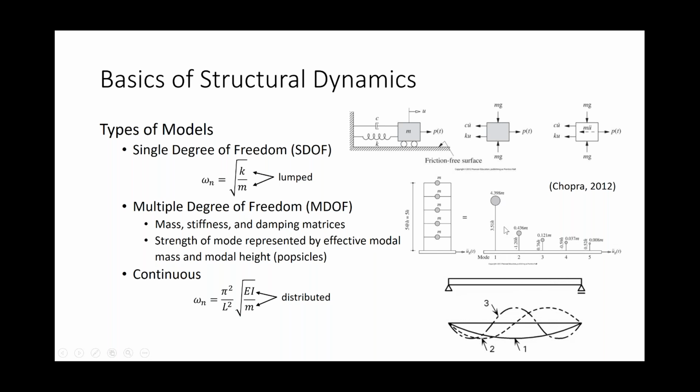which gives you kind of a nice way of considering this physically. You try to shake a popsicle that has a very long stick and a very heavy mass at the top. It's going to have a fairly low frequency. And as you go and reduce that mass and reduce that height, you have a higher frequency structure. So that's representative of the modes that this beam might move through, where the fundamental mode, or this half sine wave in mode 1, is going to occur at the lowest frequency. Mode 2 and mode 3 would occur at higher frequencies.